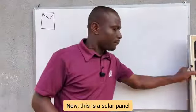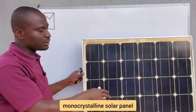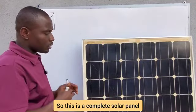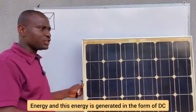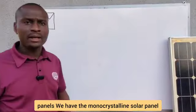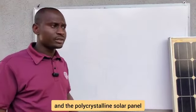Now, this is a solar panel. The solar panel is made up of cells. This panel here is a 72 cell monocrystalline solar panel. When you connect cells together, it will form what we call a solar panel. So this is a complete solar panel. When you expose this solar panel to the sun, the cells start generating energy, and this energy is generated in the form of DC, that is direct current. For solar panels, we have the monocrystalline solar panel, the polycrystalline solar panel, and the amorphous solar panel. The ones that are commonly used are the monocrystalline and the polycrystalline solar panel.